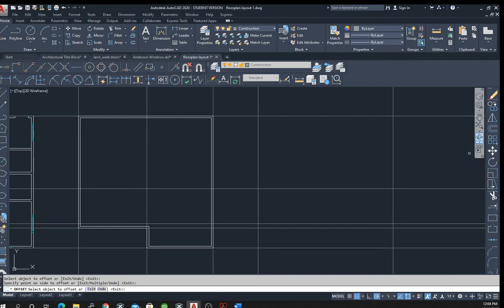And then we're going to add another foot for, again, our flooring. Our joists, the 2 by 10s or whatever that dimensional lumber is to build our floor, and then our subfloor and whatever floor covering is above it. So we'll add 1 more foot, and do another offset. Finally, we have another floor to ceiling height, 8 feet.